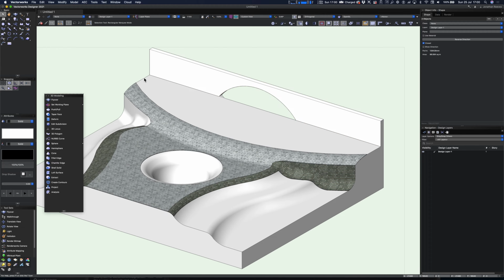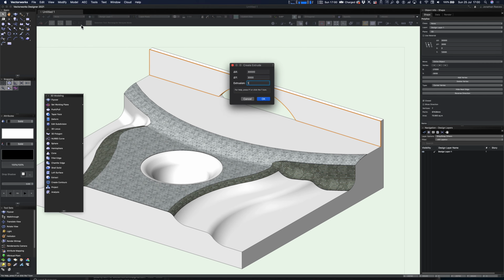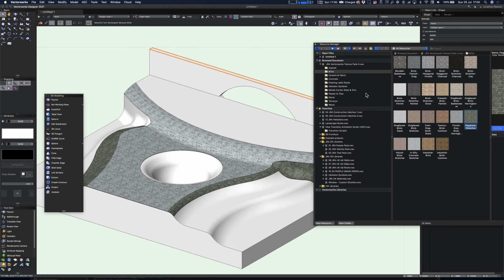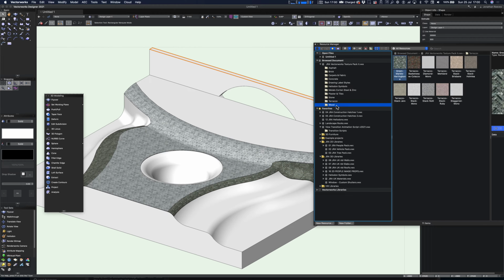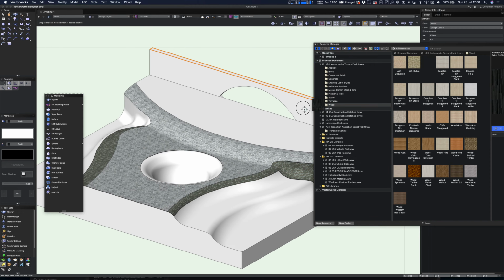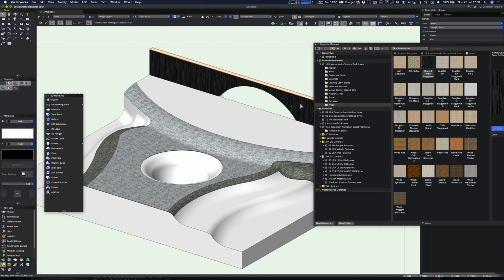So I think what we'll do is extract the textures from the wall. Let's ungroup them, and then we simply click on them and do Command E, Model Extrude. Just bring them out 1 mil. 1 mil is the minimum you need, like a wallpaper really, just to assign some nice texture. So we're going to go on and put some really cool timber cladding, I think, on those.